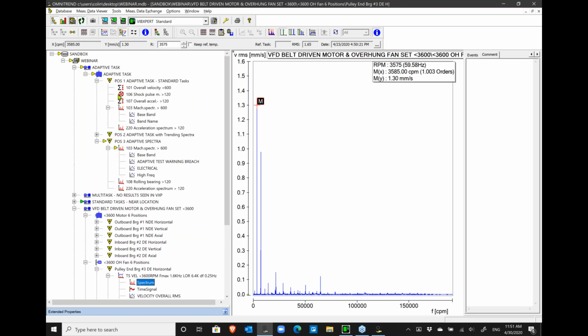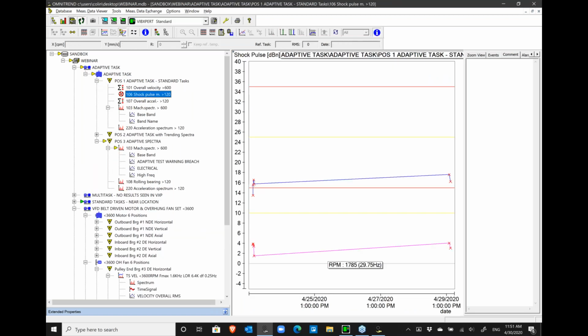Yeah, we covered shock pulse on the setups when we were looking at the VivExpert on the last webinar. Shock pulse is an ultrasonic check that the PRUFTECHNIK sensor can carry out. It's measured at 36 kilohertz, which is well in the ultrasonic frequency. And what we've got is the background noise in the bearing, this pink line here, we call that the carpet value, okay? So this number here, and this is a special number. And then we have the maximum number heard, which is this one here at the top, okay? So the maximum number is the peaks that are causing the shocks that are in the bearing, so any damage in the bearing. And what we're looking for is a gap of around 10 decibels.